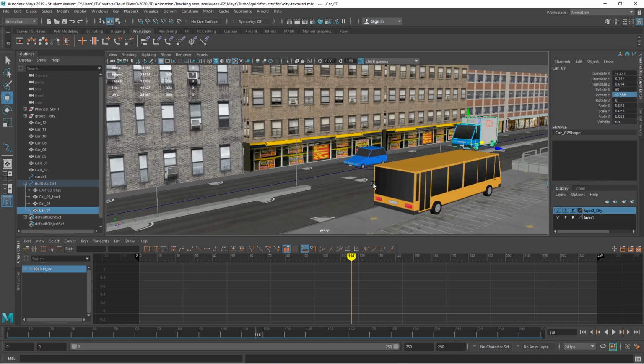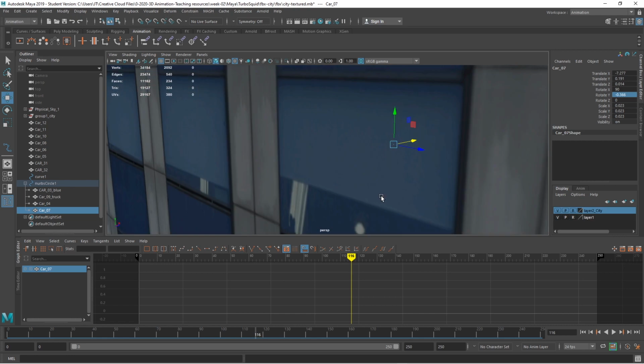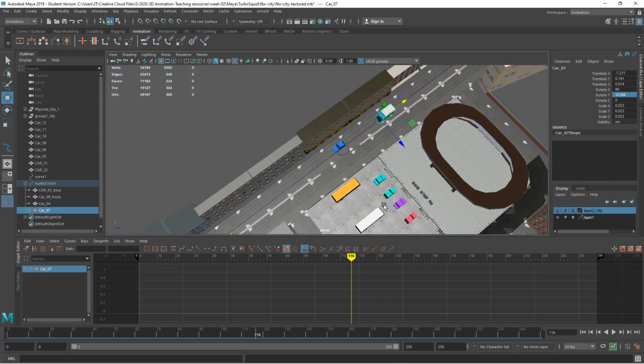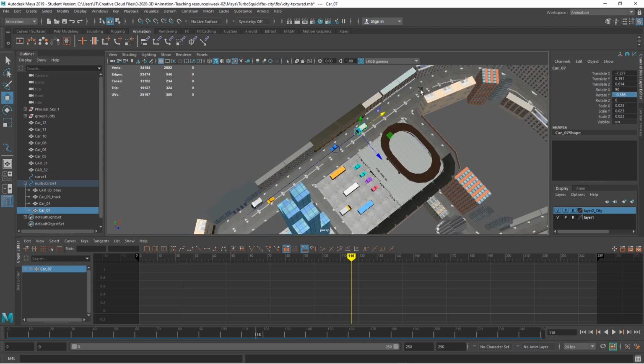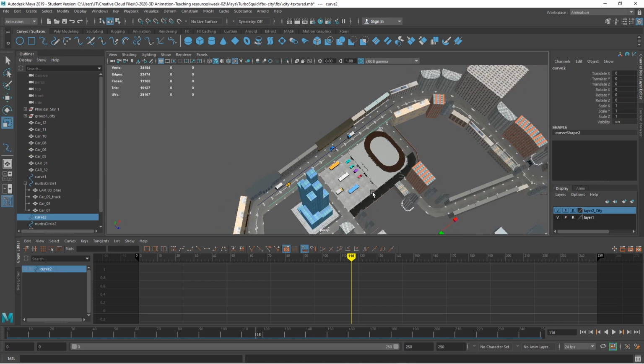So that's setting up a motion path. I'll set one up the other way. Last time I did it, I started at this top end and drew down to that end. I'm going to do it the other way around now. So I'm going to select the EP curve tool here and click here, and then it will end up over here. Similarly again, a Nurbs Circle, which I want to scale up.